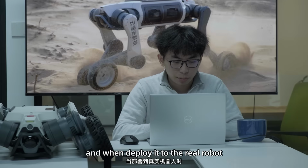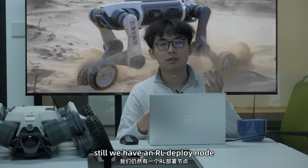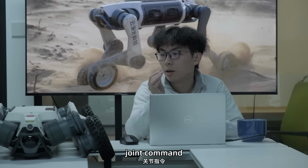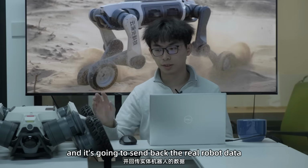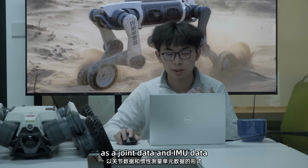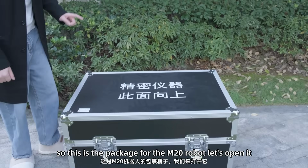When deploying to the real robot, we just switch this Magic simulation to the real robot. Still, we have an IO deploy node. It's going to publish the joint command, but the real robot is going to have another ROS node to receive it, and it's going to send back the real robot data as joint data and IMU data. Now we can begin our sim-to-real test. So this is the package for the M20 robot. Let's open it.